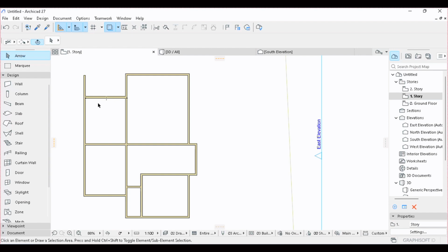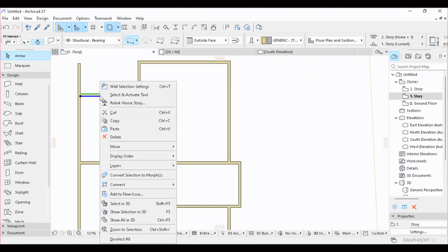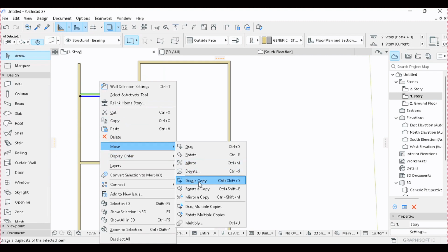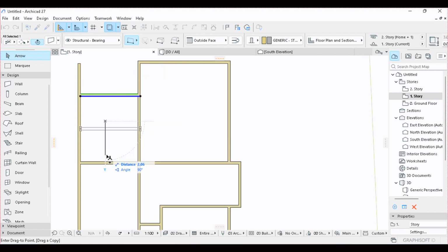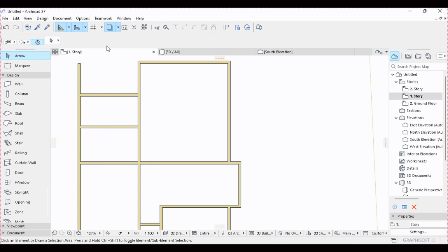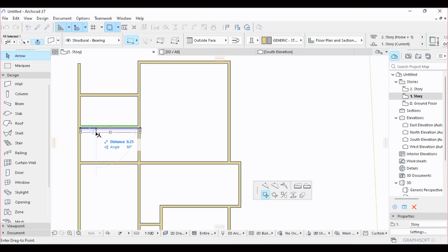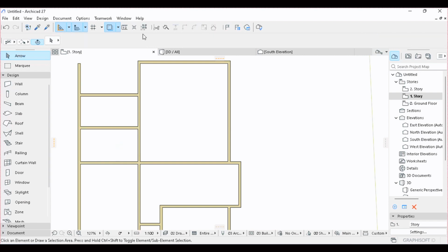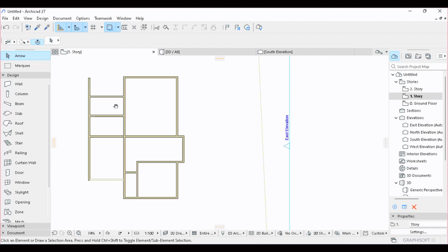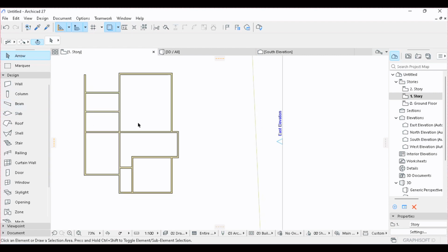So to be able to do that, we'll click this wall here and copy it by 1.95 so that we can have a dressing of at least 1.80. Preferably I would like to add the 0.05 to the dressing, so I'll click the wall and type 0.05, so that our toilet can be 2 meters and our dressing 1.85. So now we have the concept of our client.